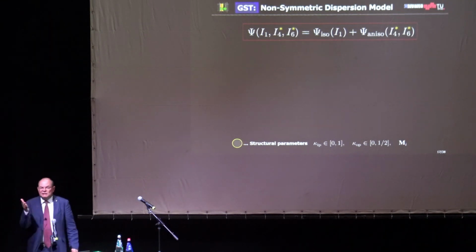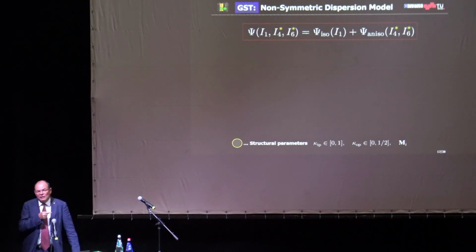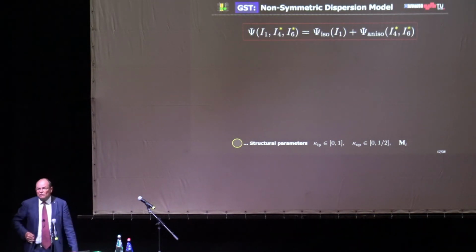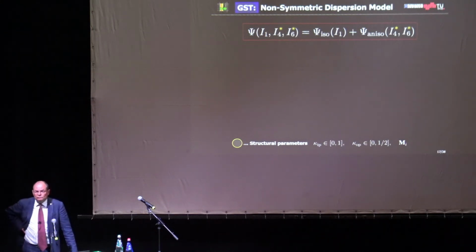So Q1P0, I don't know if you... Which code did you use? Well, we used FEAP for the development, but we have implemented this also in Abaqus, and this is also a mixed element that we have chosen there. So it's a UMAT code that we wrote basically. But this you can take from Abaqus basically, without doing anything. Okay, thank you. But you need a mixed formulation.